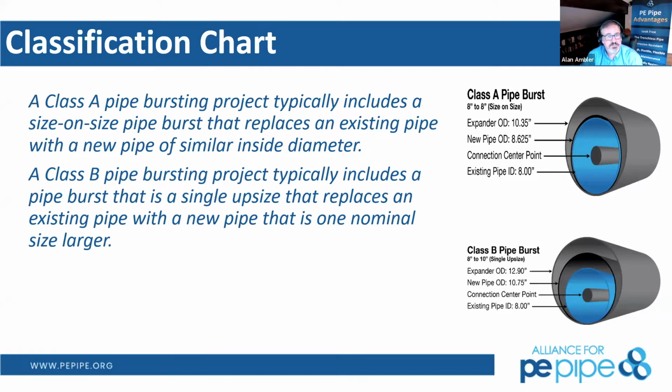So Cornelius O'Connor asked a question about sags in sanitary sewer pipe. Sags in a sanitary sewer pipe are basically going to be a void of material underneath that pipeline that provides us with an area in which we may very well get accumulation of grease or other debris. Pipe bursting will not correct a sag. It can smooth them out.